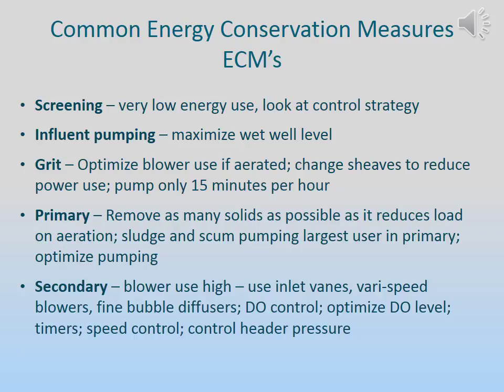Influent pumping. Remember the impact of pressure on pumping cost. Can the wet well operating level be adjusted to reduce the pumping head? Just a small decrease in pressure or head can save 2 to 4% or more in energy.